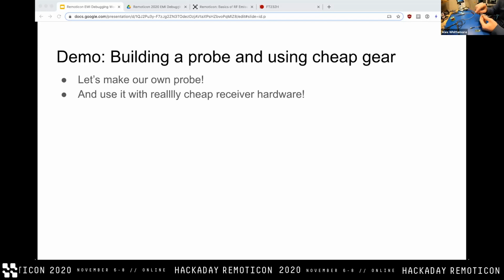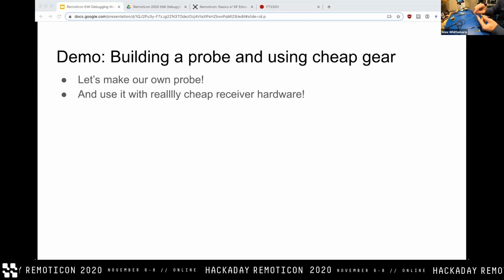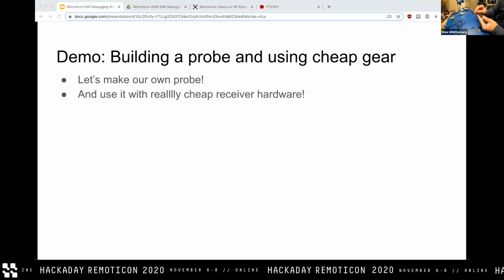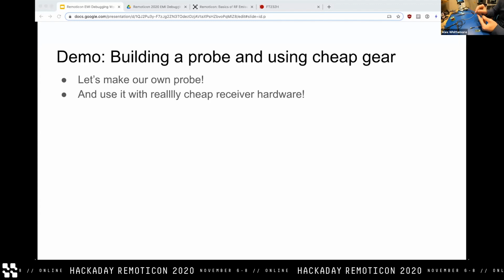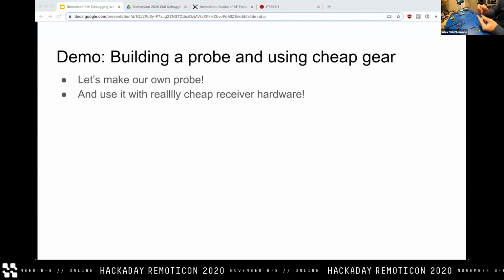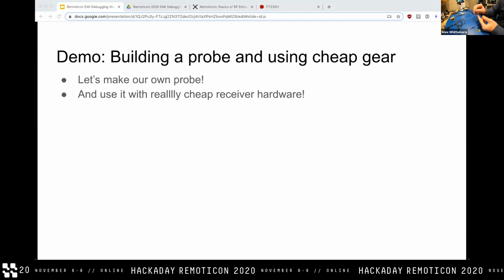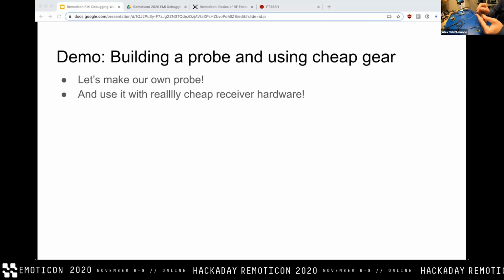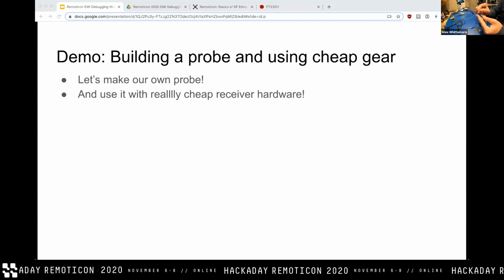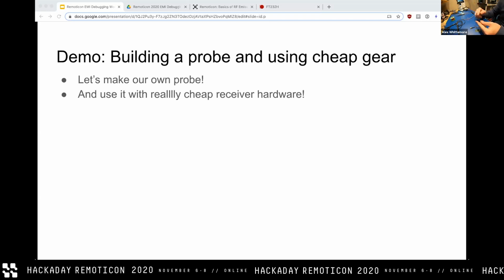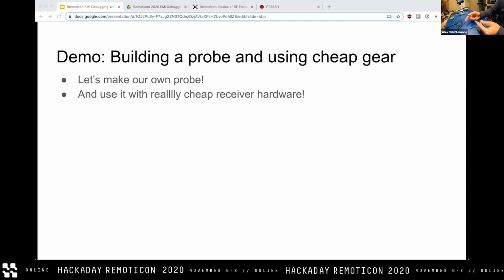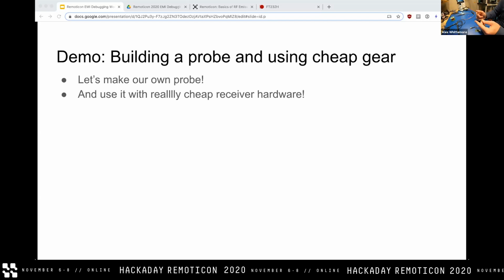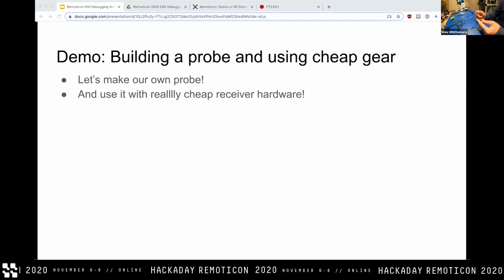If we look down here, the probe theoretically should be insensitive to any magnetic field in this region because, one, the induced voltage is proportional to loop area. The loop area is really tiny on any of these individual little twists. And also they alternate direction each time. So it's effectively if you wound a transformer one way for one turn and then the other way for the next turn and then the other and so on, so that basically every turn just canceled itself out and the net output of the transformer is 0.